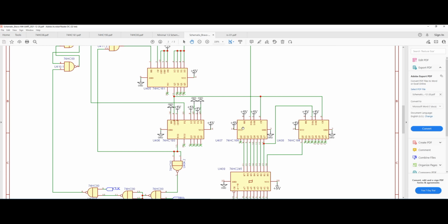Remember from the order of the bits. Therefore, if you actually shift those bits one by one, what will happen is that the first bit of the data is going to end up on Q0 of the second chip, because again, the shifting is going to happen from left to right. But if you remember, we also have a stop bit, which is the last bit, and it's a high bit. And that high bit is actually going to land on Q0.